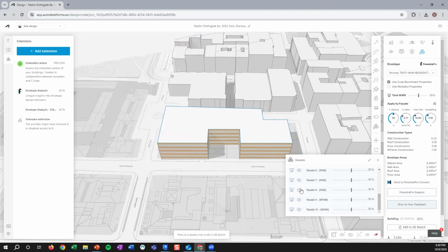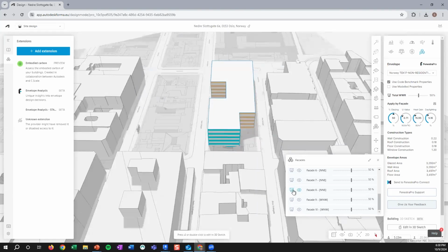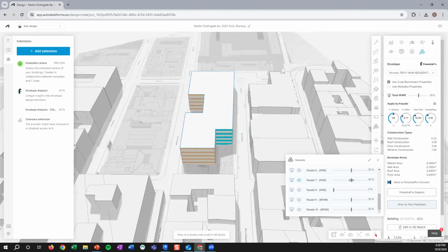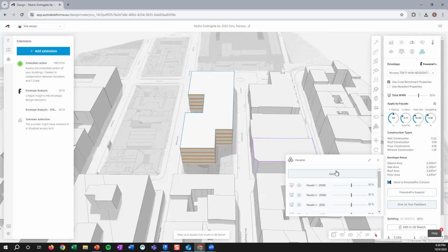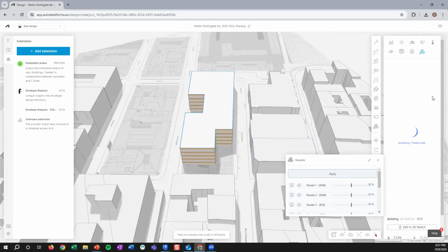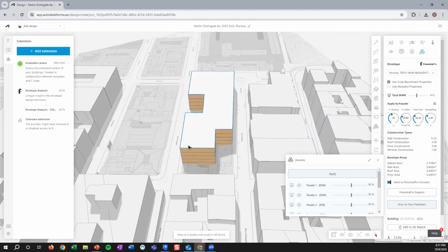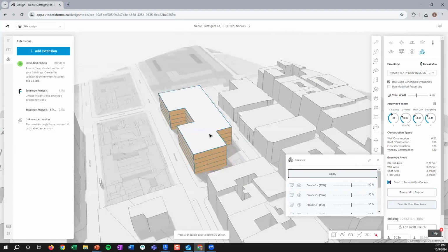Let's say these northeast facades, I may want to say, for whatever reason, there is 0% percentage shading on these. I can change each facade as I go, and apply those, and my model will update. It will change from a total of 50% to something lower, because remember, I have 50% on loads of facades, but 0% on these three facades that I just changed.